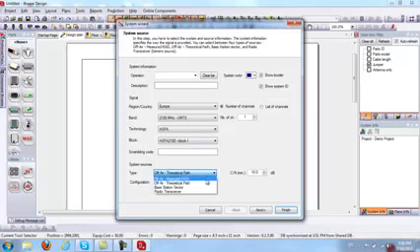Just a quick note here, the first 2, off-air measured RSSI and off-air theoretical path, are used when the in-building design is part of the macro site. And in that case, a donor antenna will be needed at the rooftop to actually import signal inside the building. The second 2 are used when there is a dedicated base station providing coverage to the building. So in my case, I will do base station sector.